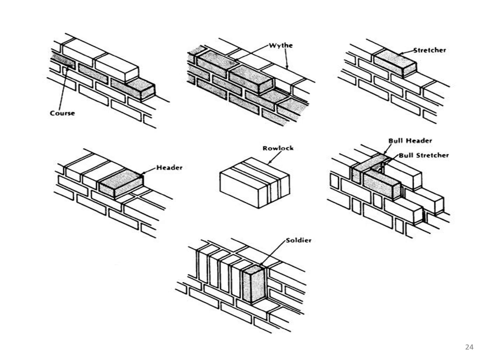Now you have a few other types that aren't shown here, but they're called the soldier course. The soldier actually is down there on the bottom in the middle. That's when they're standing up. And now it's easy. We like to think of a soldier course, if you want to remember which type of brick it is and it's standing up. Think of a soldier standing at attention. Those are used in different places, sometimes over windows and under windows. It gives an architectural look, but it also has a little bit of a reason behind it for structural and for maybe catching up on the rows. But here the bricks are stacked straight up.